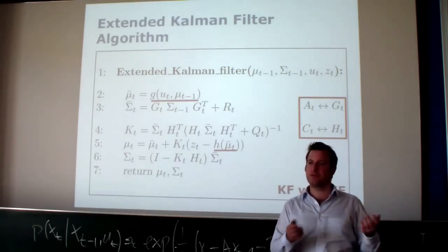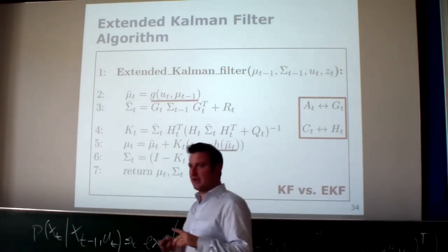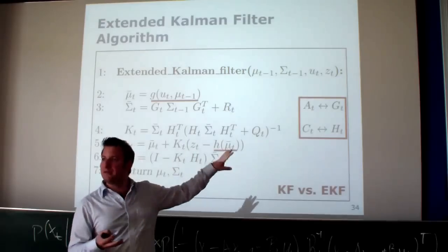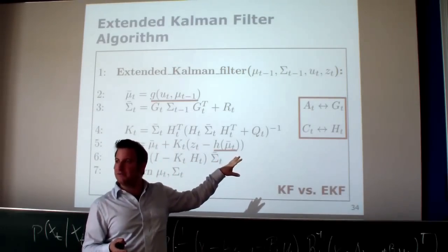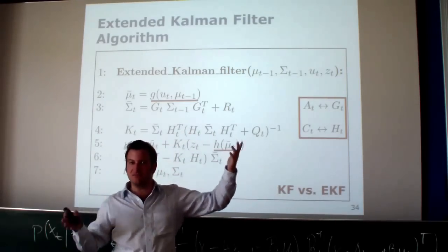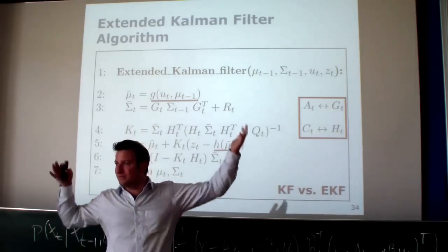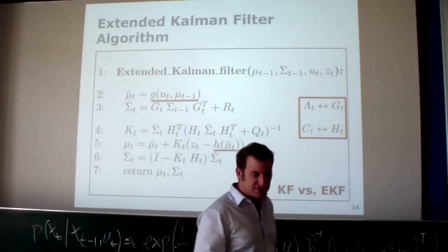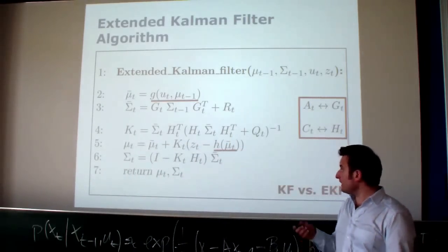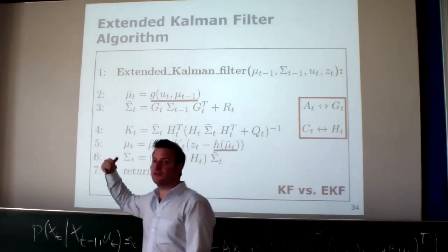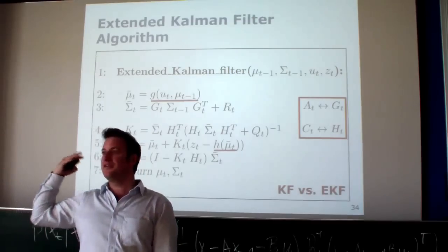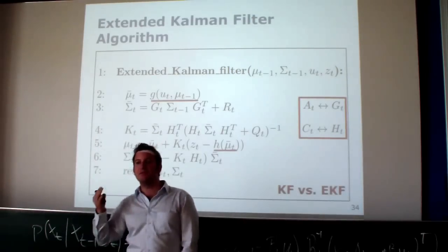The Kalman filter has the property of being optimal for the linear case with Gaussians. But if you're back in the linear case, the EKF gives the same result as the Kalman filter, because if you linearize a linear function, the Jacobian is 1. So nothing changes in here. For the linear case it's still fine to use the extended Kalman filter, but as soon as your functions become nonlinear, the extended Kalman filter is not an optimal estimator.